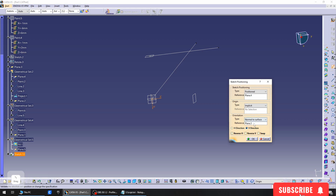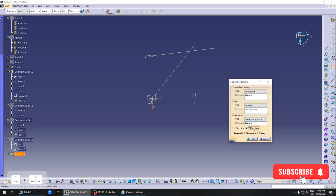Okay, you can obviously choose which direction you want it to be. You want it to match this reference. It's either the V or the H, vertical or horizontal. The other one is 90 degrees to that, and you can choose to reverse H or reverse V, and you can swap them together. And that's it for how you define your sketch.